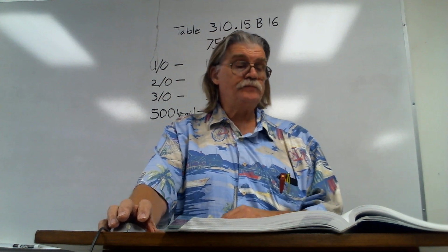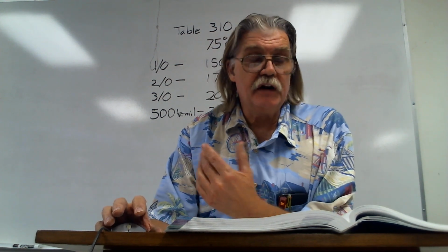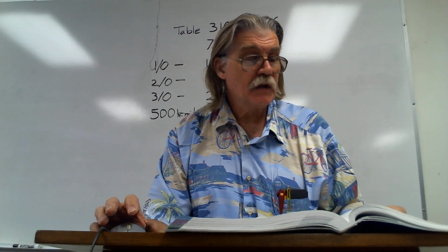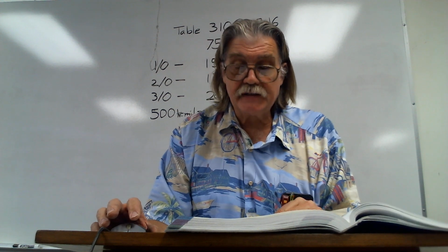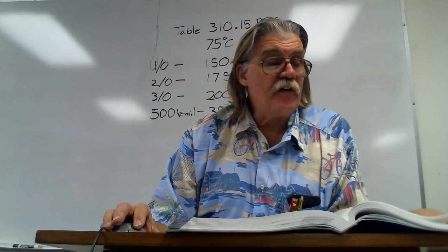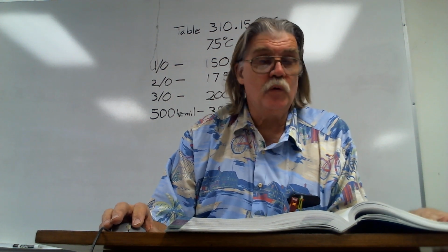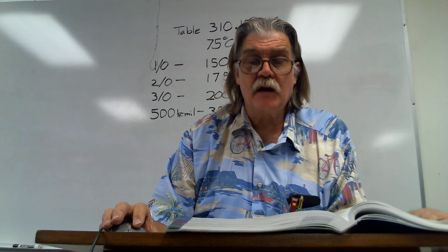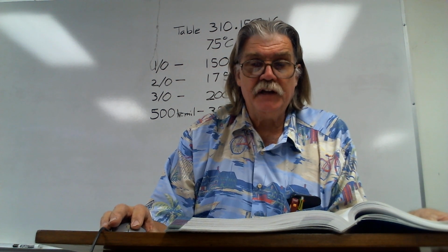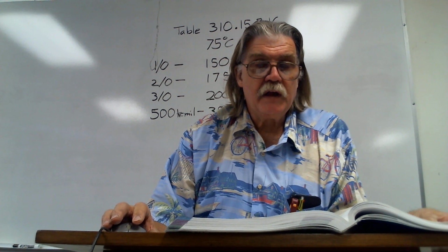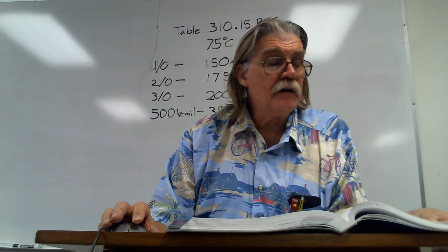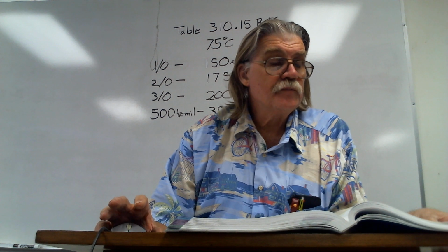Okay, so what we would do here is find out the rating of the actual compressor itself, right? And we would take that and multiply it by our 225%. And in your Mike Holt book, he even has a little example if you wanted to go there. It would be on page 206 of your Mike Holt book. And if you need to get there, I'll pause for a moment. Okay, so hopefully you've gotten there. If not, remember, pause the video.